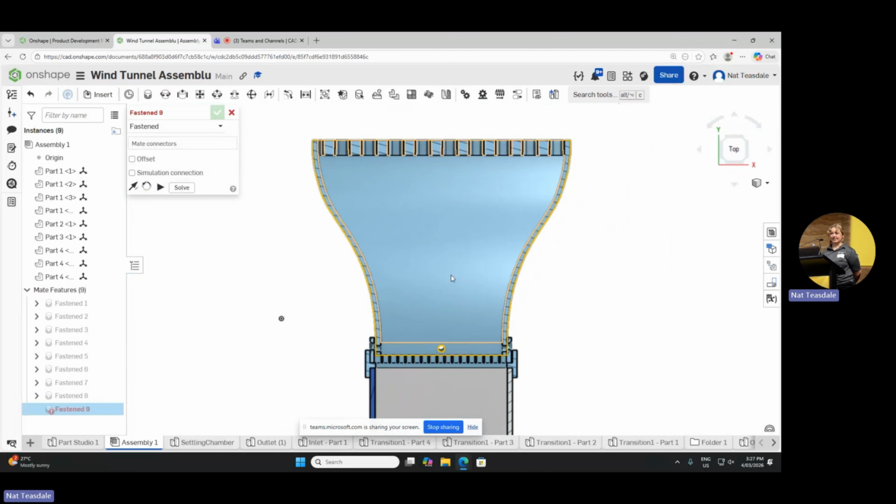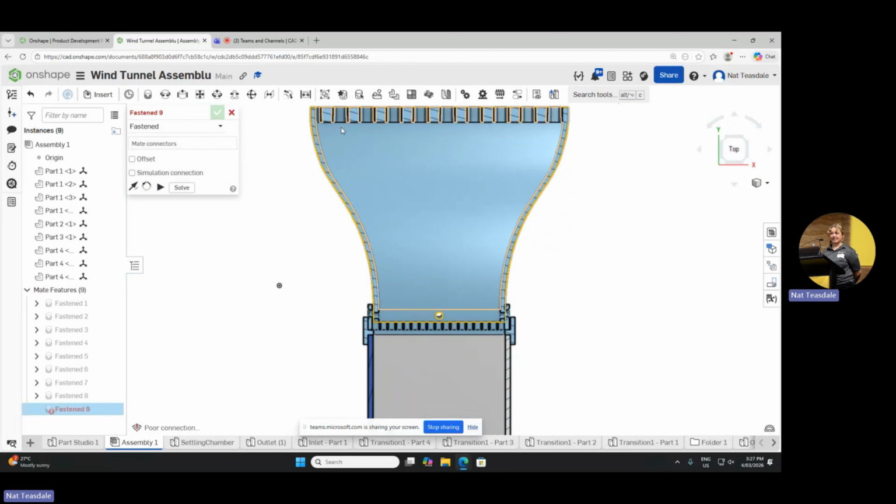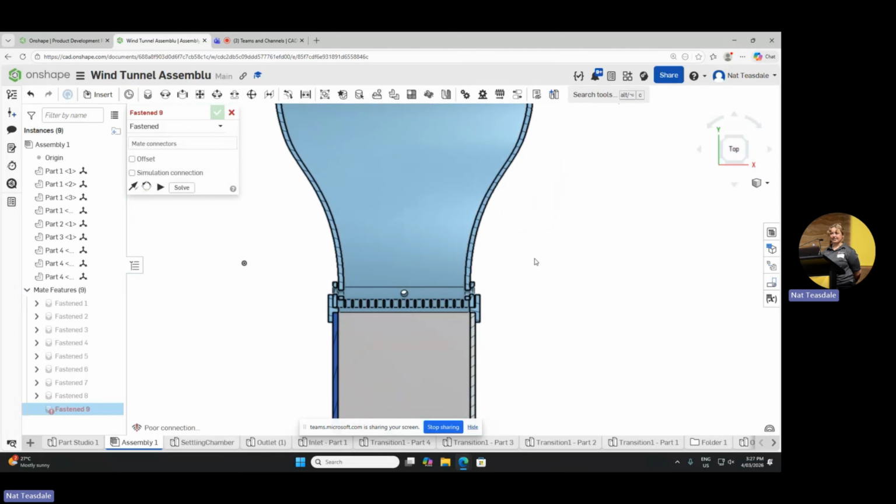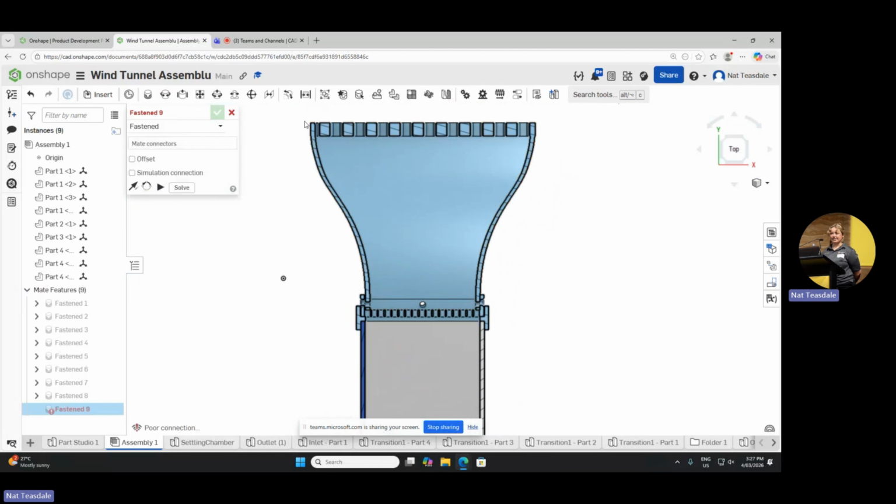The inlet is specifically designed to give us the acceleration of airflow using the shape while not completely destroying the entire geometry of the airflow as it travels into the second settling chamber. So you can see right here, if we were to go with something straight, we would be pushing air coming in on the edges into an angle they don't want to be at, creating vortices.